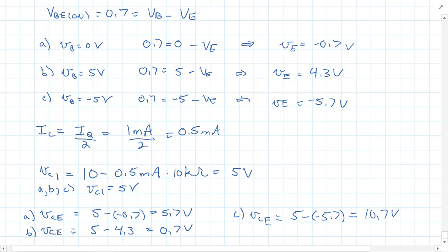But then if you have 10.7 times 0.5, well, that would be 5.35 milliwatts. And that's important because when you're talking about a data sheet, there's what are considered maximum ratings, but you really don't want to be running at maximum ratings. Those are what it can absolutely handle.